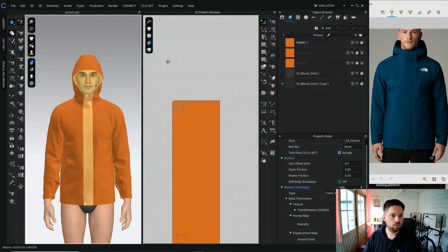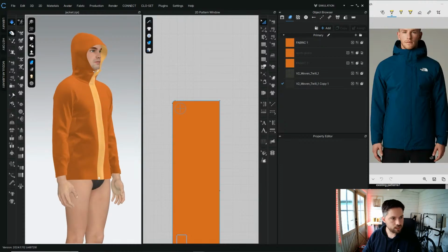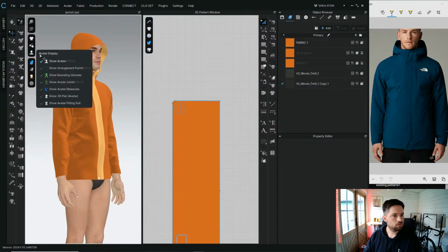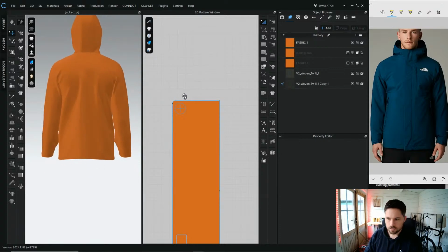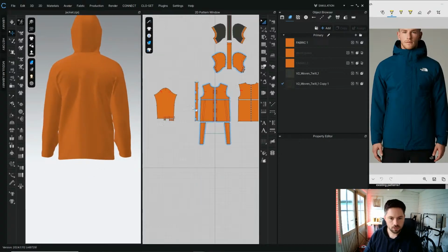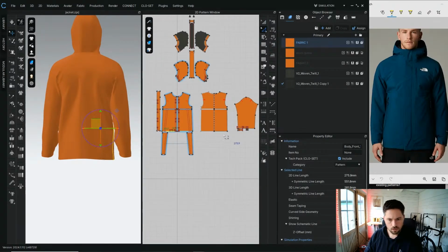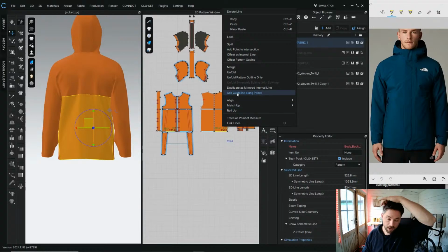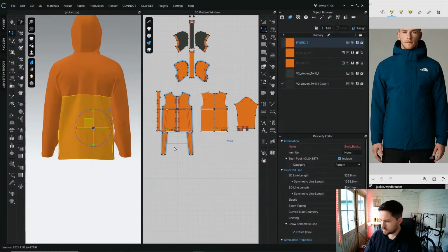Okay. No worries. Alright, so I'm changing the skin offset so it makes it a bit more padded. Definitely need to bring that waistband in. Let's get rid of Thomas for a second. So at the back, yeah, you can see I definitely need to bring it in. So what I'm going to do is create a panel at the bottom. So offset internal will be 30 centimeters.